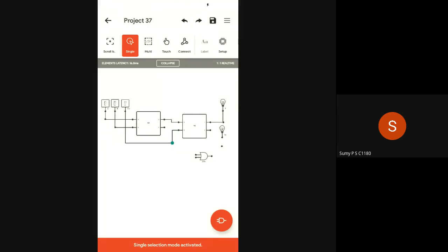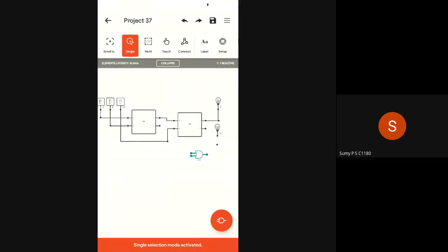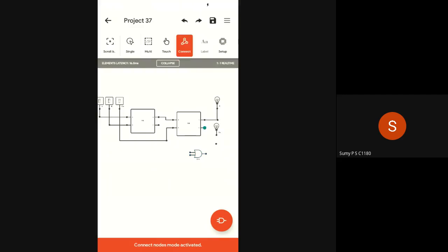Second input we have given. Like I said, using nodes you can reorient anywhere. Fine. For this OR gate, one input is from your second half adder, the other input carry is from your first half adder. Fine. So this will be the final output of your circuit.